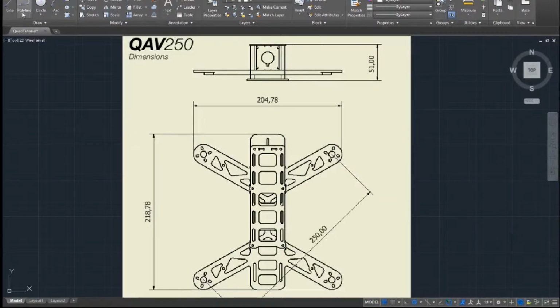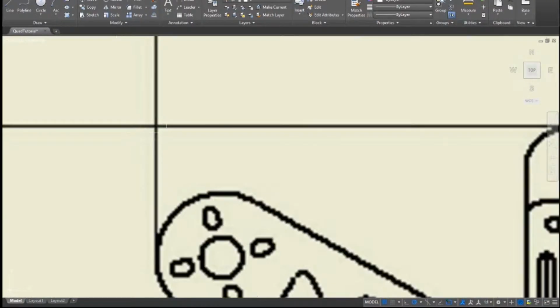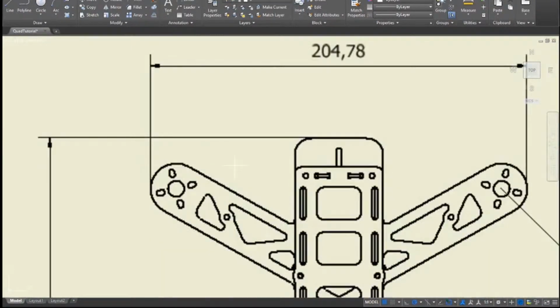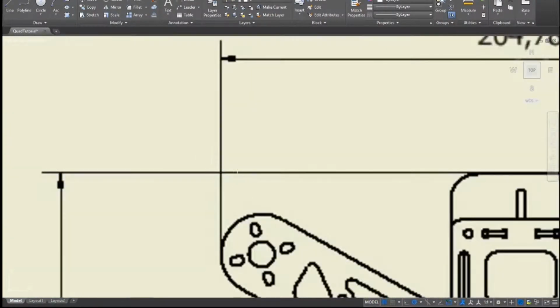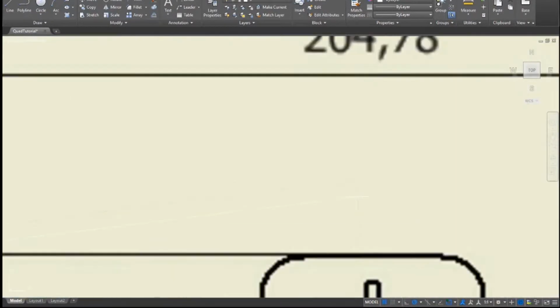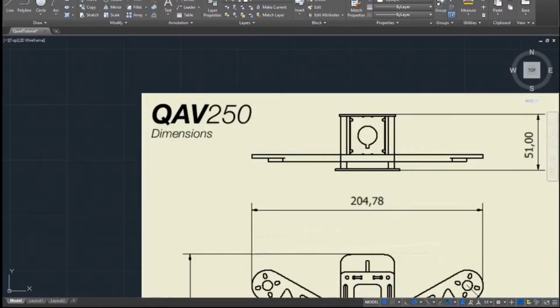All right, so now let's get started. We're going to want to start off with the line tool. You're going to see this cross up here. What we're going to do is split this into different quadrants. We're going to do one quadrant, and then we're going to copy it over to quadrant 2, quadrant 3, and then quadrant 4. So we're going to start out here. See this cross right here? Line up your cross with that. All right. Boom, and then we're going to want to drag that over. Make sure that you see the dotted green line. That means you're going at a 0-degree angle.